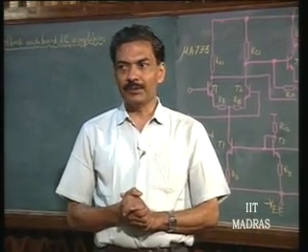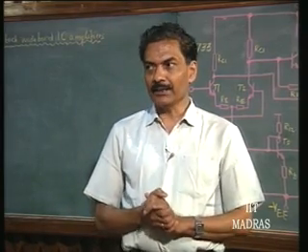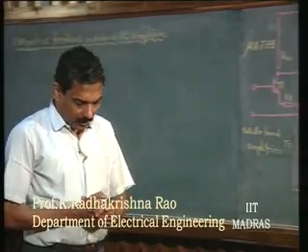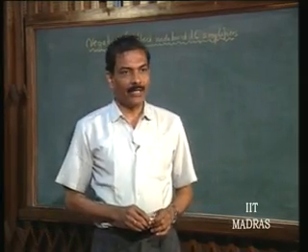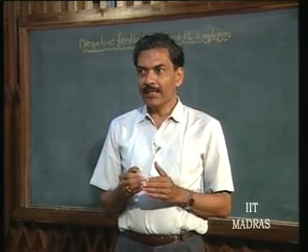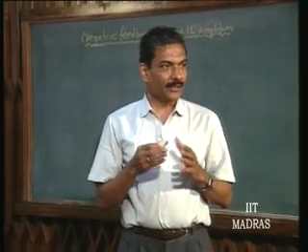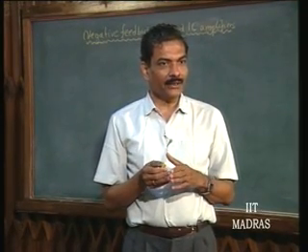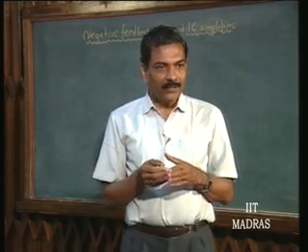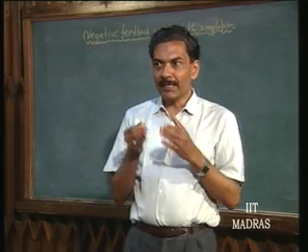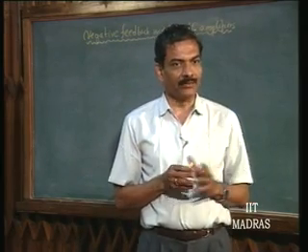So, ultimately we will go to negative feedback wideband integrated circuits, amplifiers. So, let us now just revise our knowledge about negative feedback. We had seen earlier that negative feedback we have to give cautiously. In case negative feedback is likely to turn itself into a positive feedback and result in oscillation, that is a dangerous thing, because we have to cut down the oscillations by introducing a dominant pole, and that will cut down the bandwidth further. So, if at all we use negative feedback, the negative feedback amplifier should not need any frequency compensation. That is the condition of negative feedback that we must utilize in widebanding.